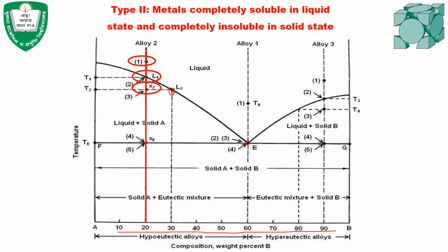Okay. So when the temperature reaches the eutectic temperature, the liquid has a composition of 40A 60B. And what is the significance of this? This is a special composition, right? Isn't it a special composition? Yes, sir. It is the eutectic composition.